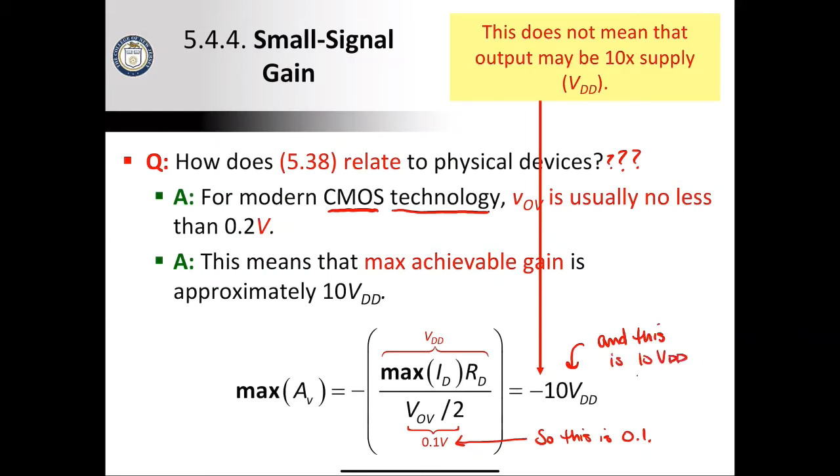Again, that depends on specifically what device you're using and some other factors. But this will be sort of like how for the small signal model in Chapter 4, we use that threshold of 5 millivolts per diode as being okay for the small signal model. This is another rule of thumb that we'll be using.